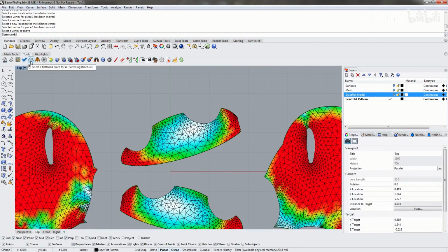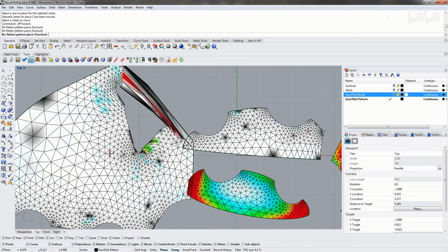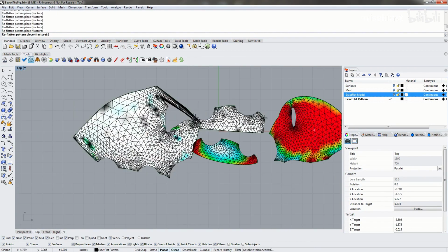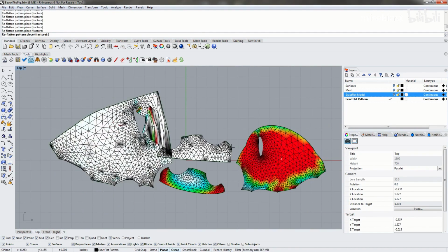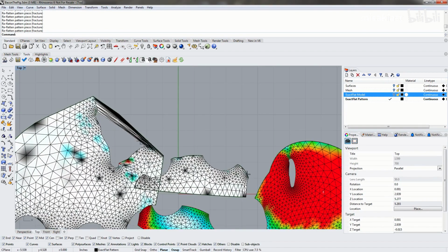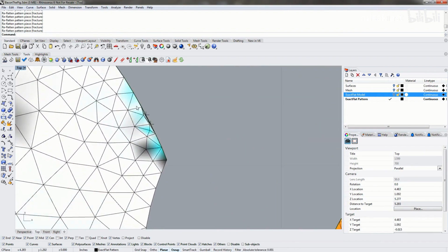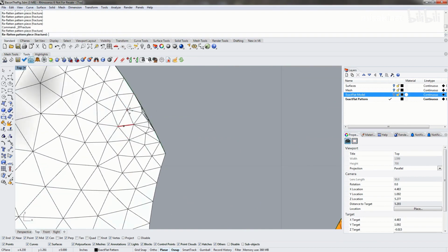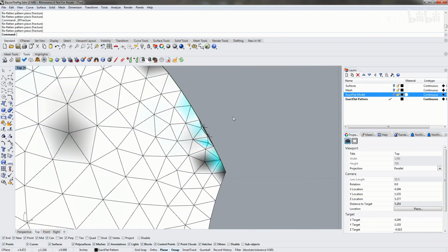Lastly, I'm going to try to create a bad mesh using the fracture tool here. If we've got a mesh that none of the tools are working on to remove the flip triangles or the folds or wrinkles, we'll use this one as an example over here. We can see we've got some flip triangles right here. We can use the exact flat cutting tools to cut out, whoops, I just accidentally fractured that. So I'm just going to fracture this again. So we've got our flip triangles back over here.